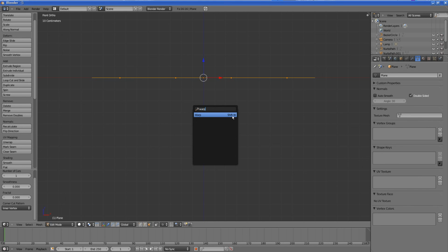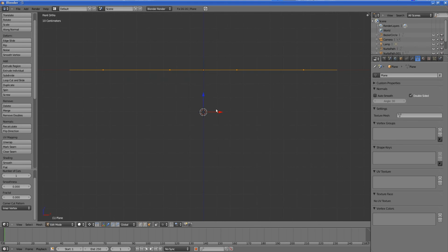The hotkey is Shift W, and before I do this I need to switch to the 3D cursor mode. Again remember the transform manipulator moves to the pivot point mode. Since the pivot point mode is the 3D cursor, the manipulator has moved to the 3D cursor. If I change it back to bounding box center, it goes there.